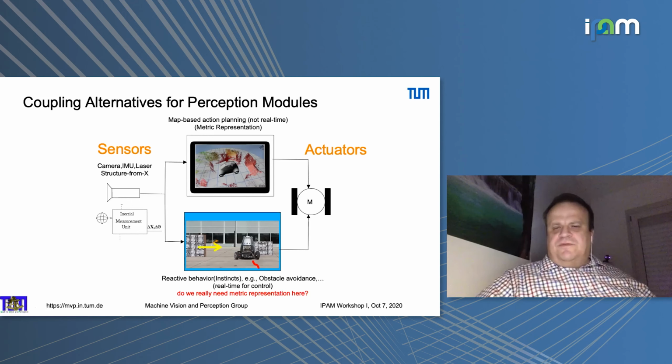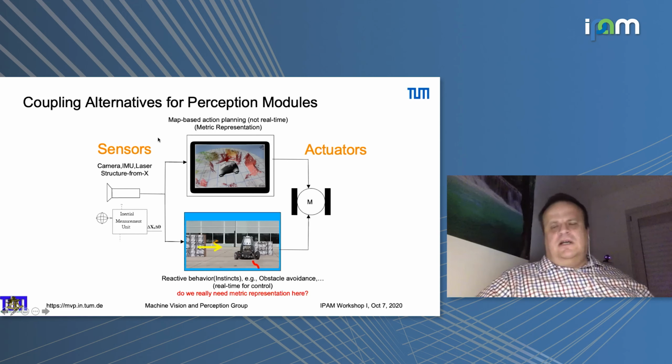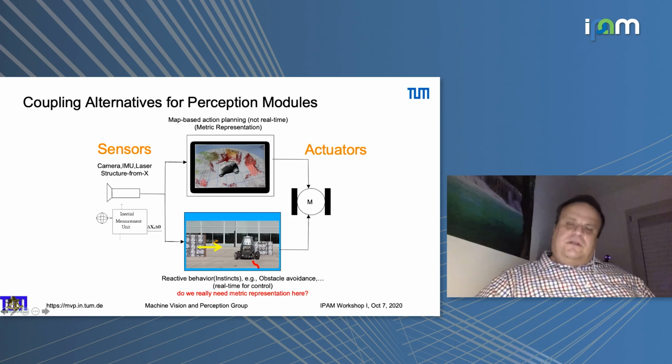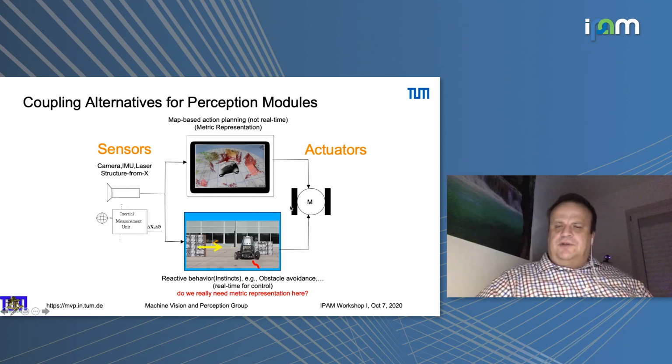What's the problem with such a chain? The 3D is not a native space of a camera. That means abstracting the information creates already errors due to calibration errors. The same is true on the other side. To go from the metric information to the actuator, you add additional errors to it, and you deal with quite a large error between what you see and what you interact with. So I'm looking for a different way how to actually combine directly the sensor perception to actuators in a more native way. We will talk about this in a moment.